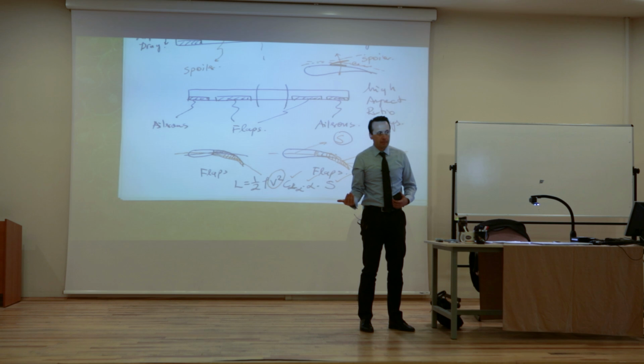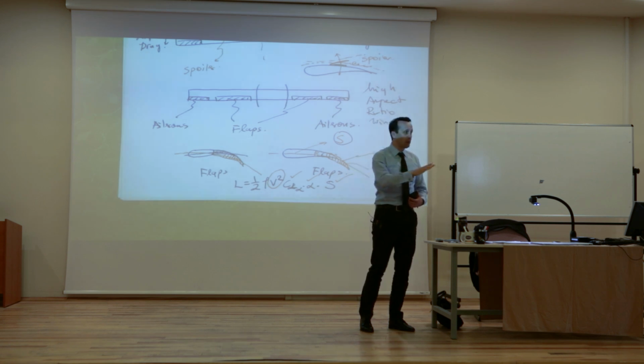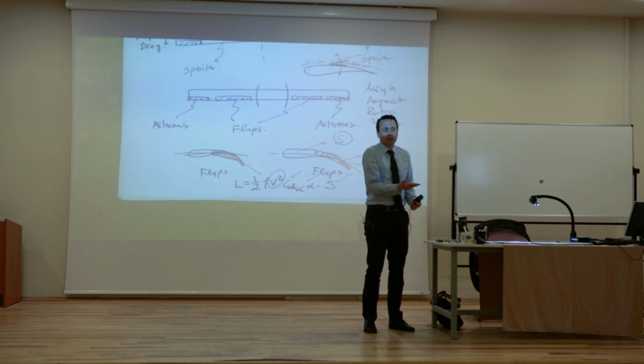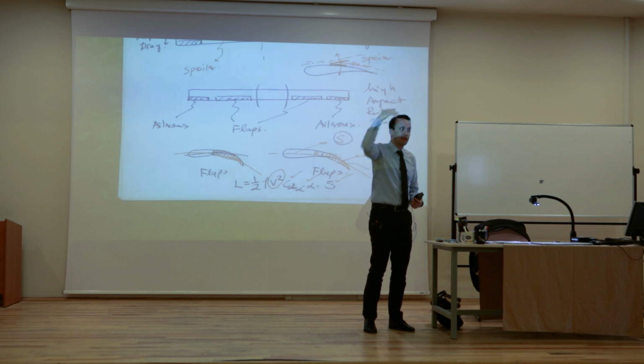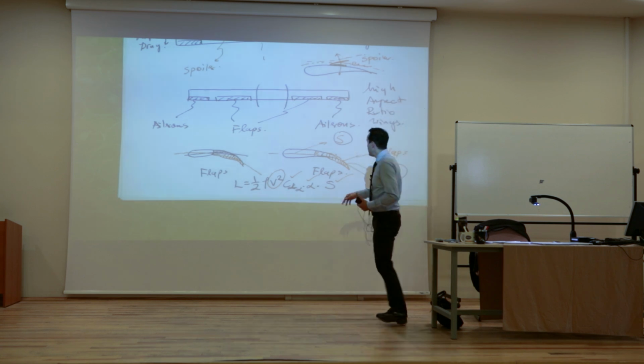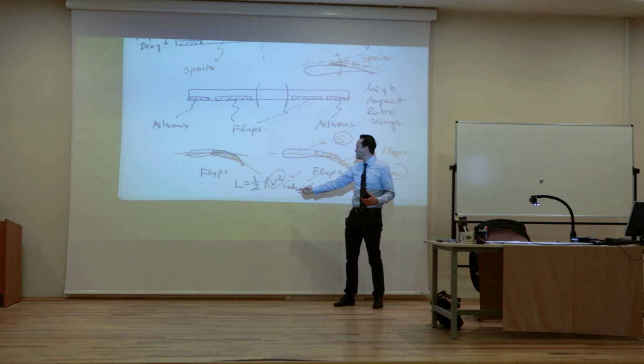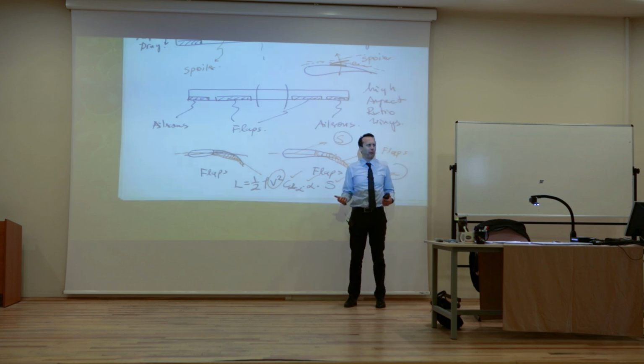Isn't it? So that means that at slow velocity, at 250 kilometers per hour when you're landing, you still need the same lift as your weight, which is the same when you're flying 900 kilometers per hour. The difference is that V infinity now is a lot smaller. So what do you do during landing if this is really small? You try to increase everything in your power.